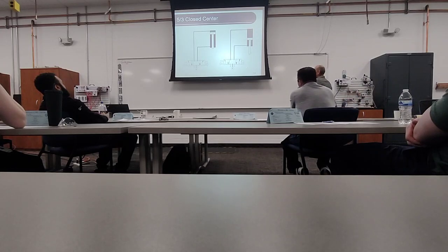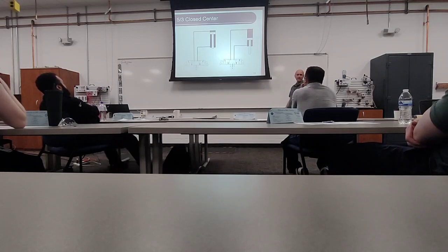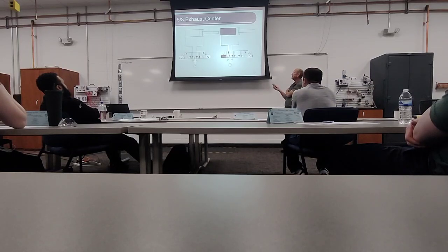All right, this is a centering type valve, and the specific one is a closed center. Is this a good application for a closed center? No. Why not? And that's the answer is correct. The cylinder's in a vertical position. This is a vertical condition. You would need some secure checks out here or something else, or a locking cylinder if you were doing this application. Typically, again, we wouldn't want to use the air to hold something in position. Air leaks off. All air leaks eventually.